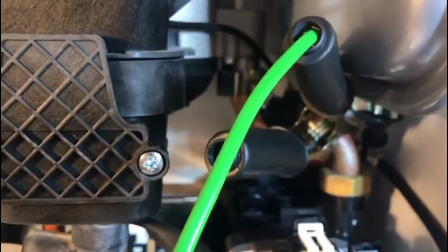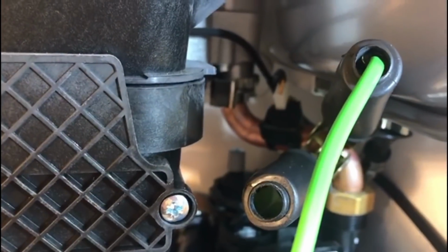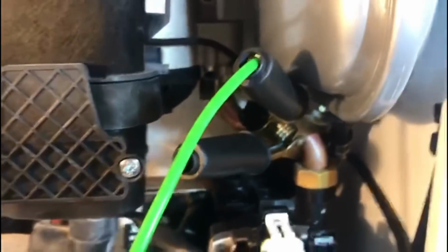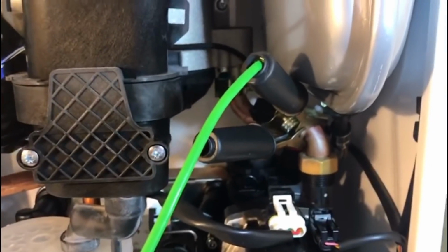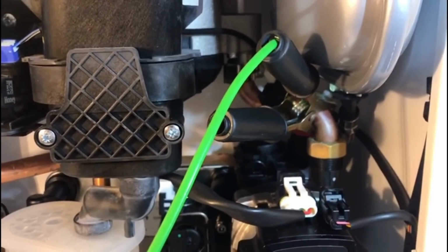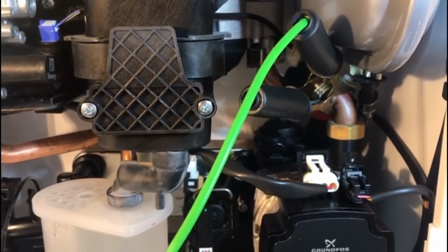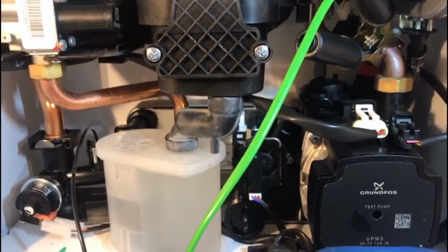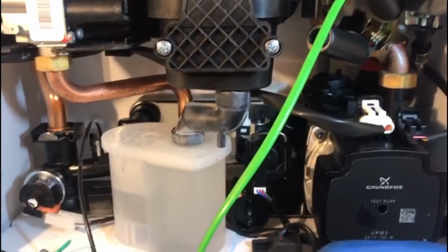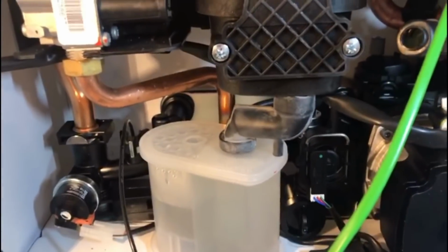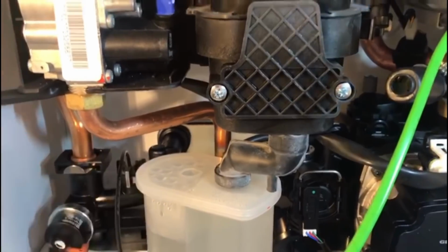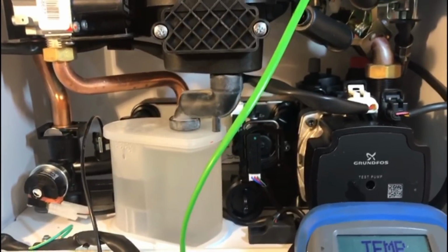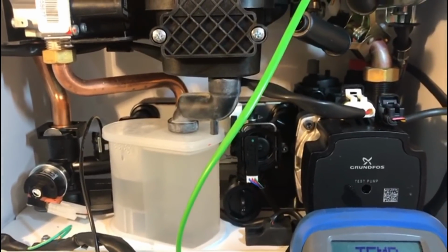There's a thermistor right next to there, I don't know if you can see. We've connected it right next to the return thermistor. The reason for that is because we use the return thermistor on this particular boiler as the hot water thermistor. If you imagine back to standard efficiency boilers, you would have had a dedicated hot water thermistor, usually on the hot water outlet of the plate heat exchanger. But for modern boilers these days, I think a lot of them use this technique.